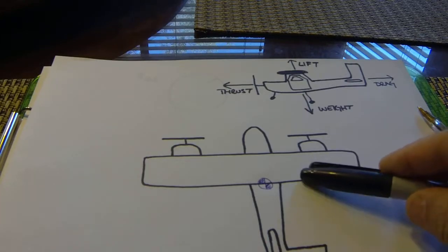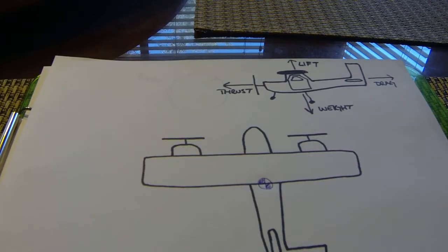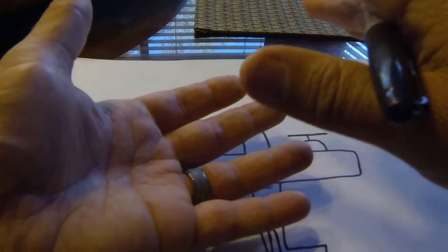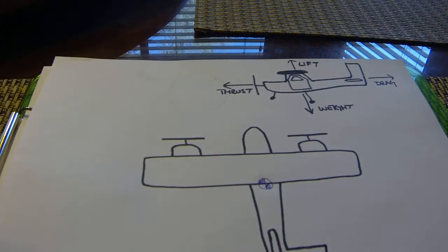Next, the airplane needs to be out of ground effect when we determine this VMC. Why is that? Well, if we think about it, ground effect provides that cushioning layer, right? That cushion of air that provides us a false sense of an ability to fly. And we've all experienced it in our single engine flying days. When you climb out of ground effect, you don't have the same climb performance as you do when you're in ground effect. So the airplane needs to be out of ground effect.